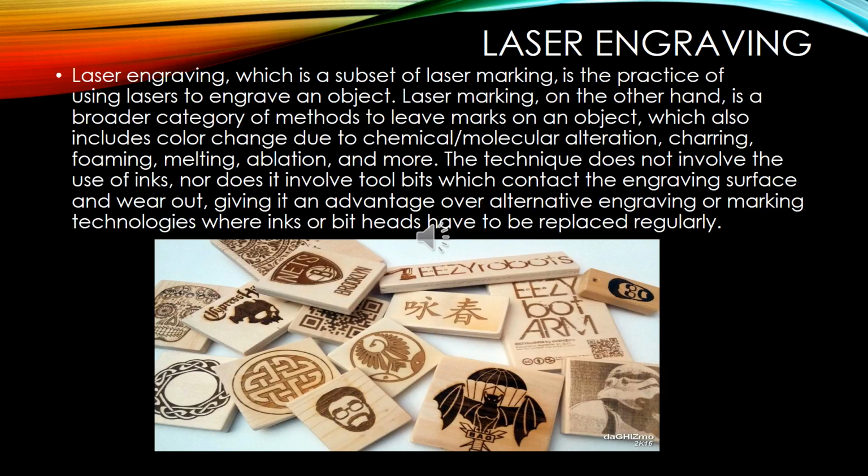Directly burning images onto wood was one of the first uses of engraving lasers. The laser power required here is often less than 10 watts, depending on the laser being used, and most are different. Hardwoods like walnut, mahogany, and maple produce good results. Softwoods can be used judiciously but tend to vaporize at less consistent depths. Burning a softwood with a fan blowing on it requires lowest power, quickest speed of cut, and enough airflow to extinguish what is trying meanwhile to ignite.